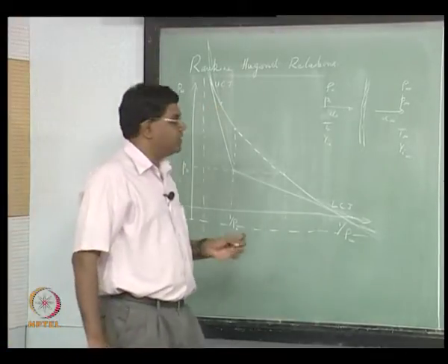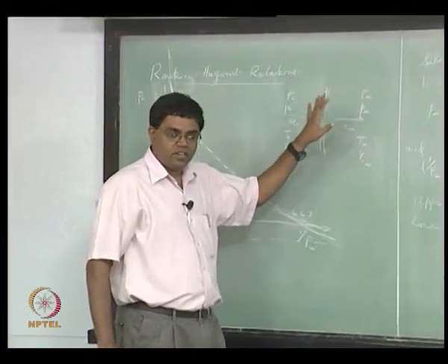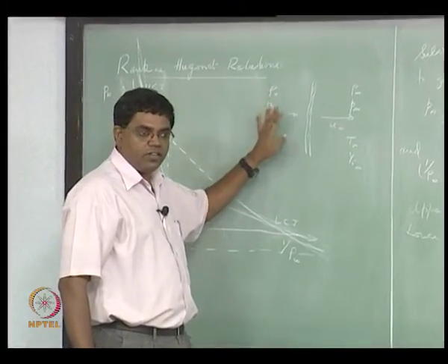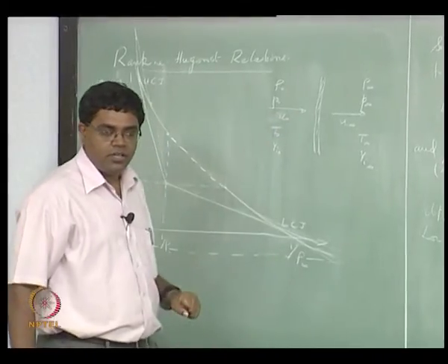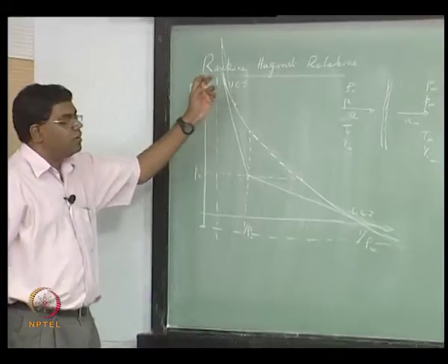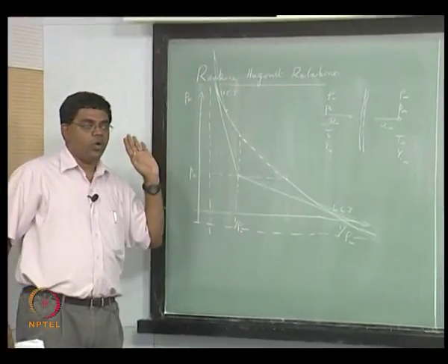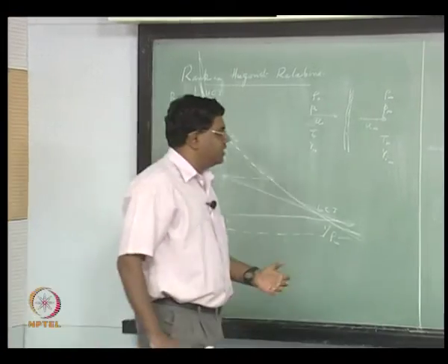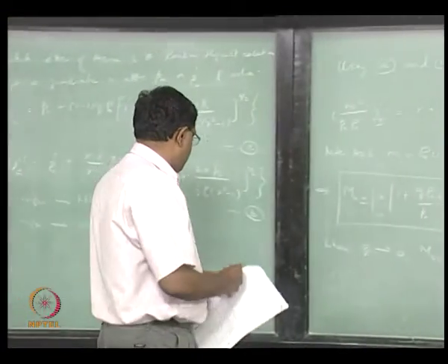So you could expect that this is not decelerated down to subsonic speeds, but it's supersonic, yet slower than the incoming supersonic speed, and therefore we need to anticipate that at the CJ point the outgoing wave is actually going at sonic conditions, right. So this is what we need to anticipate, and let's see if that's going to work out.